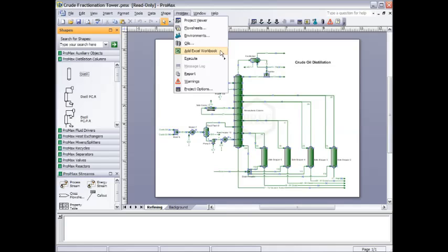The Execute button actually gives a small submenu of the options that it has. First is the Execute Project option. This will execute all blocks and flow sheets in the entirety of the project. The next option is to execute Flowsheet. Since ProMax allows you to have as many flow sheets as you would like, this gives you the option to only execute one of them easily, so you can execute your glycol dehydration unit without worrying about whether it is also executing your amine sweetening or Claus plants.